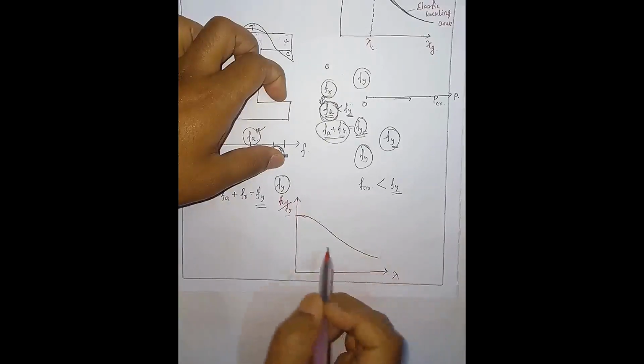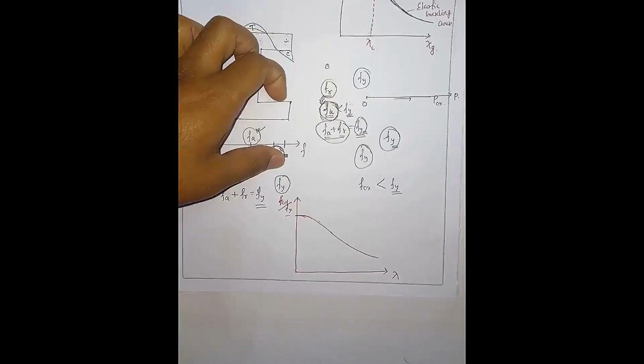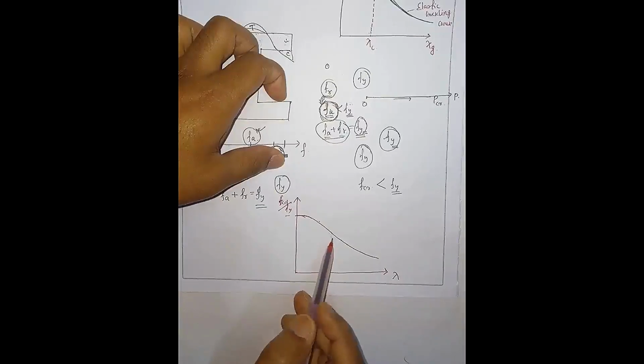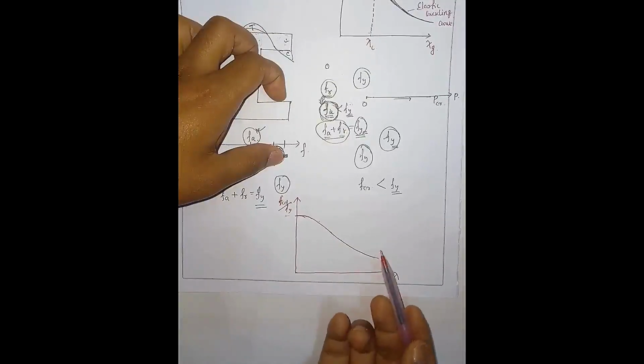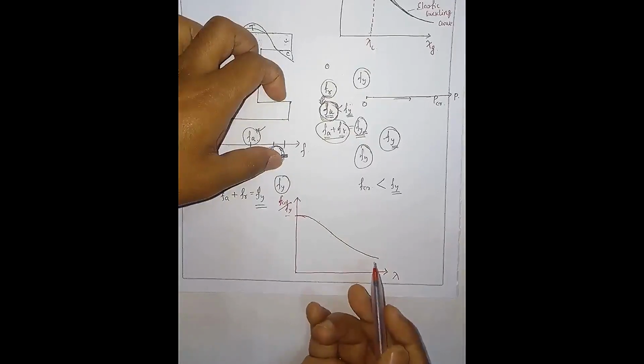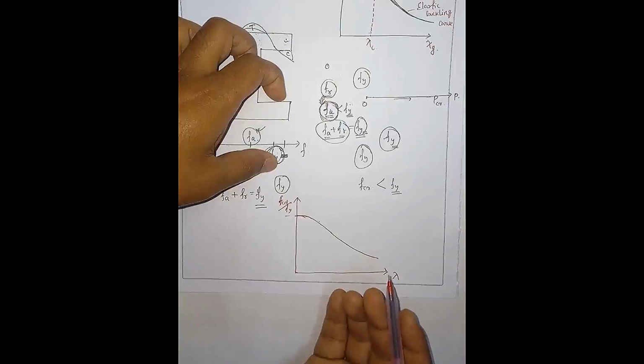I have not discussed this yet, so I will discuss it later. For different sections we have to categorize the sections based on the width by thickness ratio. Based on that ratio there are four categories of cross sections, so we will have four different curves, because for every section the behavior is different, as the governing factors are different.